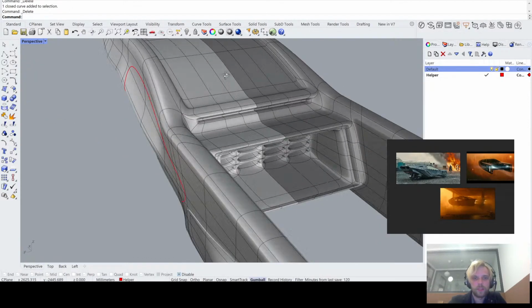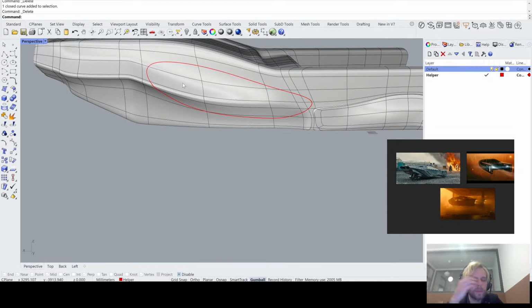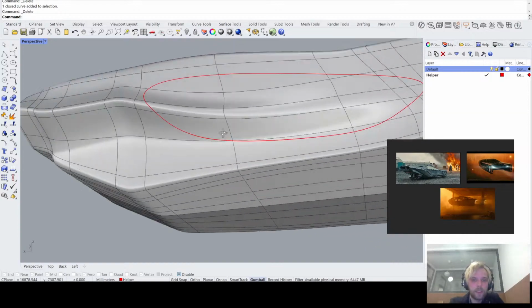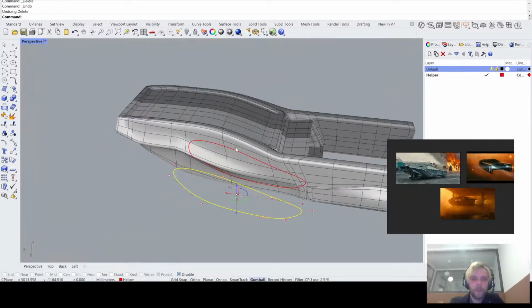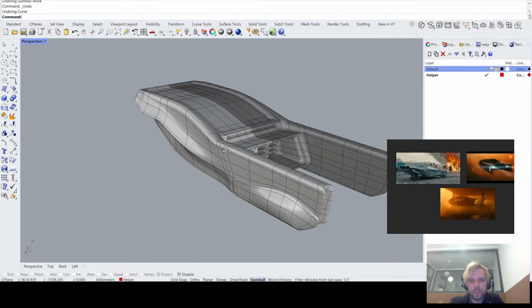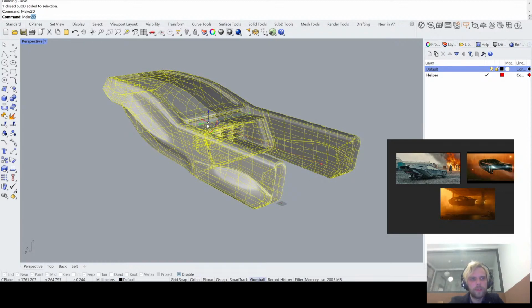And then of course you can use all of the split functionalities and so on. We will be doing that for sure. But yeah, the curve can be quite easily projected. So that's one thing. The other thing is Make2D. That's the thing that I'm interested in. Select this, Make2D. Perspective view, hidden lines. Sure, let's see the hidden lines. Let's just hit OK. Let's see if it can generate anything from this type of geometry.